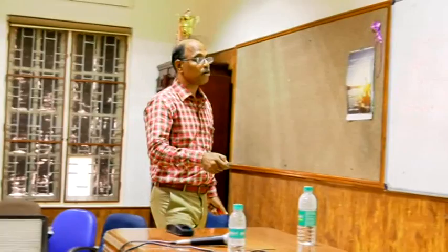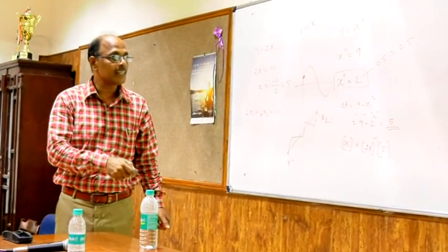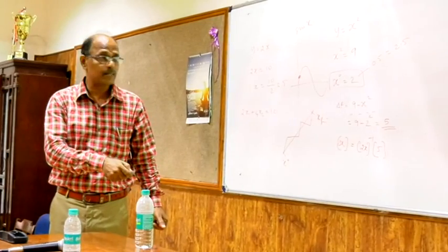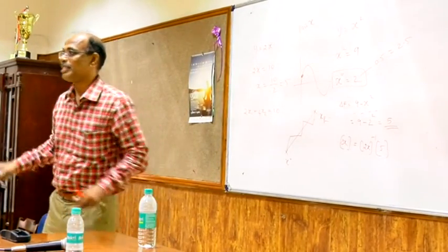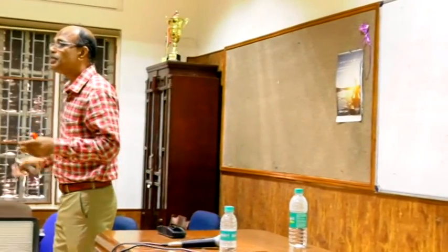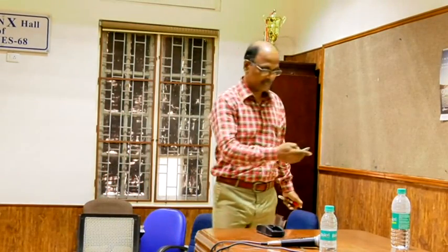So for this load flow problem, for the equations P2 to P13, delta 2 to delta 13 are the variables. Similarly for Q6 to Q13, V6 to V13 are the variables. The number of variables equals the number of equations. Clear? So these unknown parameters are to be determined at the end of the load flow analysis. That is the problem. Right?